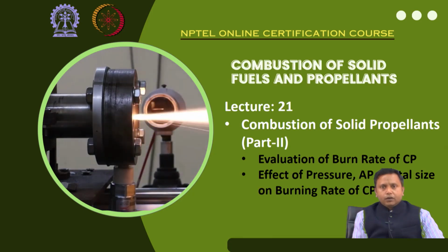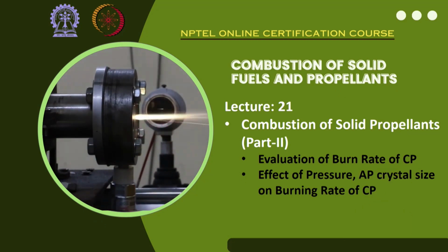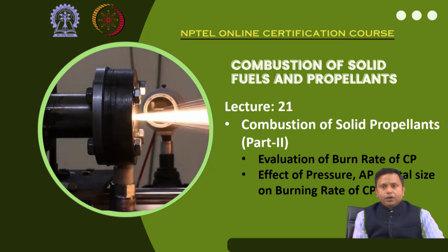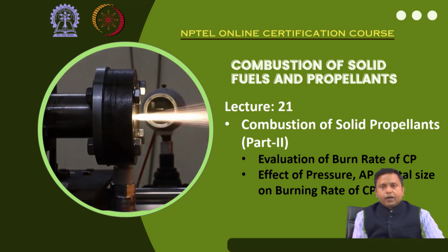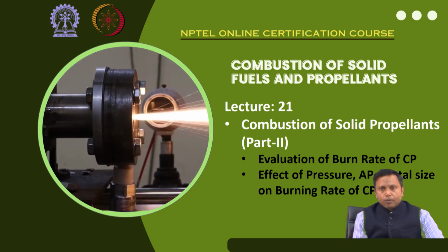Hello everyone. So we are continuing our discussion on combustion of solid propellants, and we were continuing the evaluation of burn rate of composite propellant. We have already introduced the processes involved in combustion of composite propellant. So, we will quickly look at the various processes involved, and then we will try to get a simplified mathematical model to understand the burn rate of composite propellant, and see how the burn rate is also going to be a strong function of pressure, which we have already seen in the case of double base propellant.